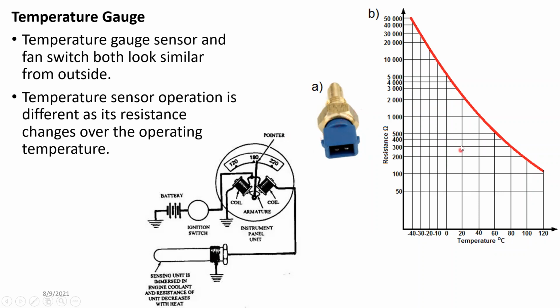So it's a very simple system. The only way to distinguish these two, if you do not know the model code or anything, is to put both of these into a hot tank at around 100 degrees Celsius, sort of like a hot water tank, and check the resistance, whether it is dropping slowly or increasing slowly. Oh yeah, one more thing. The resistance could increase with temperature, or it could decrease with temperature. Both ways can be used, and circuits can be designed both ways, because just by swapping these two the other way around, it works in the same way.